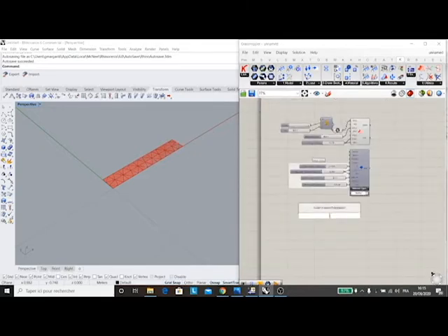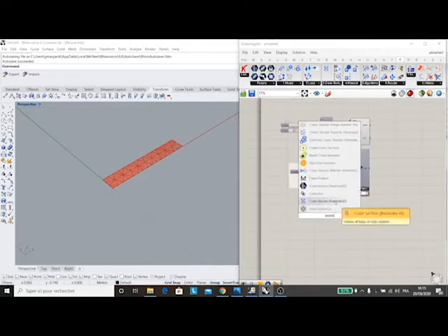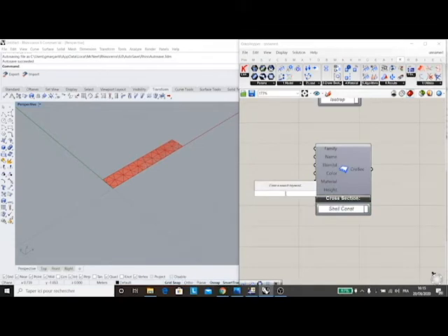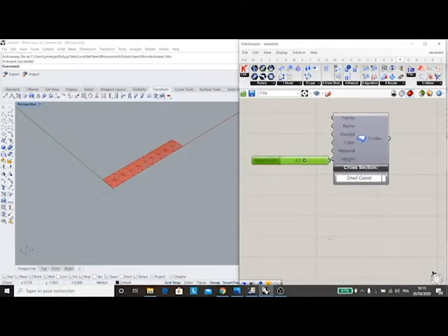So next step is to put a cross section. In this case it is the thickness of the surface. So I say shell constant and a small plate thickness. You can start with 0.5 centimeters.